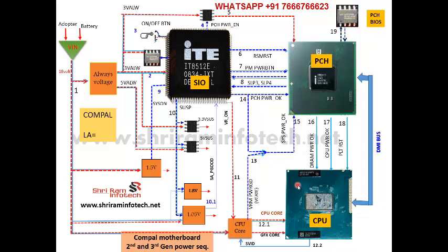When the PCH receives this system power OK signal, it will know that all power is stable, like we saw in the ladders, that every chip got voltages, and then the confirmation, power good. So this is your power good signal, which confirms that all chips got power and my whole power plant is working fine.